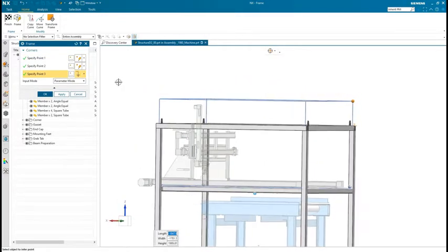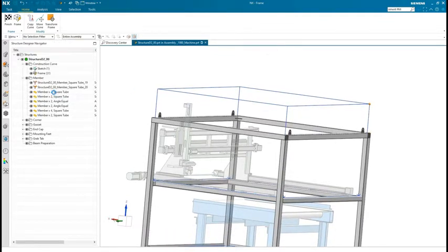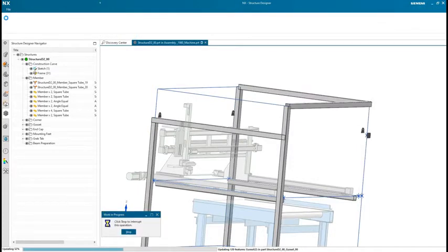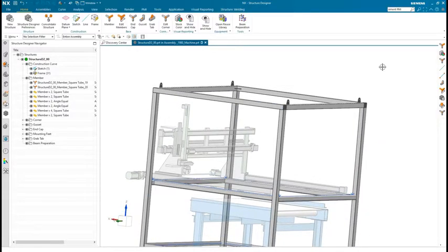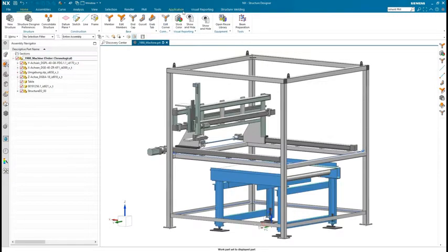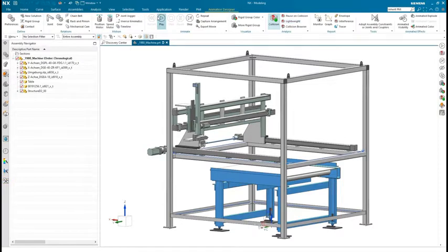Members are changed while retaining specific corner. Gussets, caps, and hoist points all update to their required location. This update process also checks members' geometric uniqueness. Should any of the identical grouped members become unique, they will be given their own group. Other types of edits can affect all members. A special command lets you select multiple members, even if based on a different stock, and change them to become the same. A quick replay of the animation shows the interference violation has been addressed.